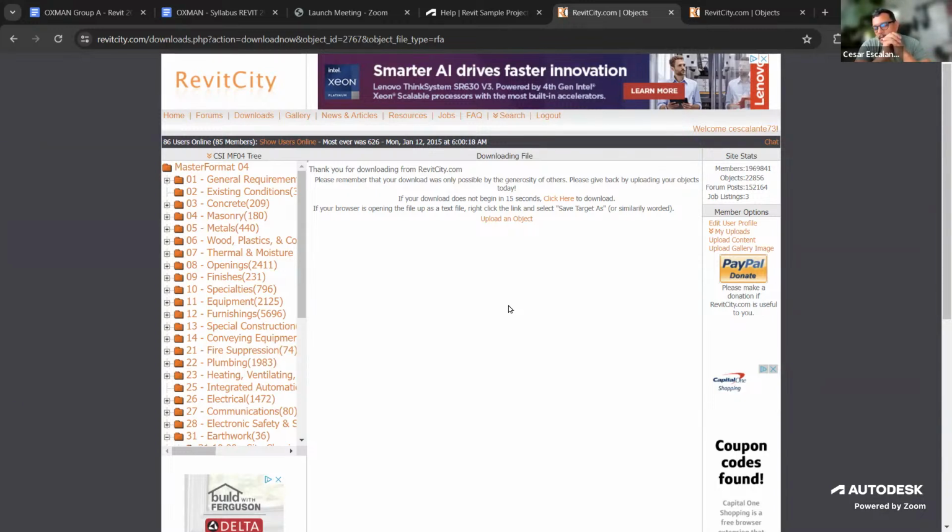I'll give you an example. When I was doing this documentation for a lab project, Steelcase, which is a renowned manufacturer, started offering the entire library of cabinetry online. When you open each of those families, it was not created natively with Revit. It was the cabinet in DWG format imported in 3D space. So it didn't have parametric properties associated with geometry.